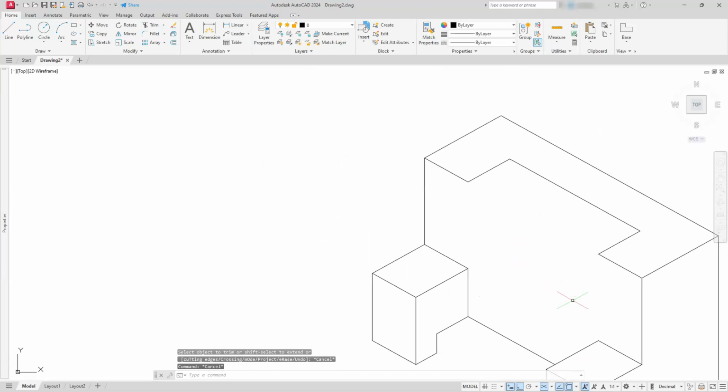Alright, let's go ahead and finish off some of this on the inside. We have to switch to isometric left. Start with the line command. Go down from that endpoint, 30. Come this direction, this is 75. And then let's go back up 30.